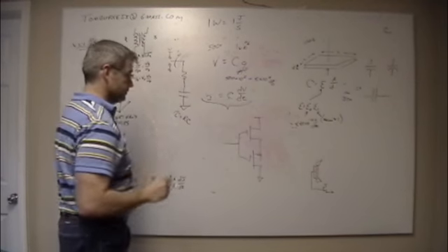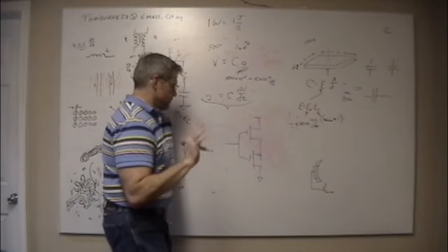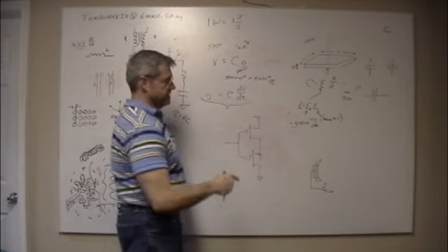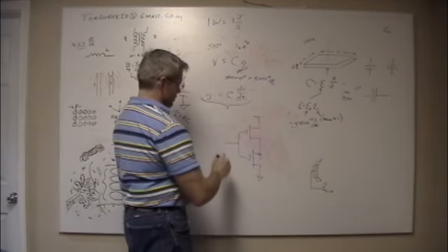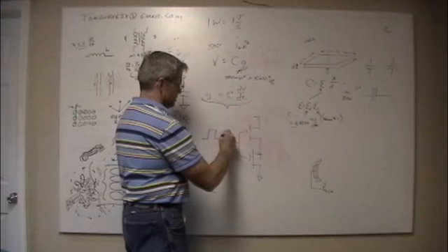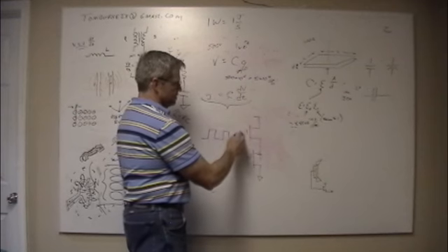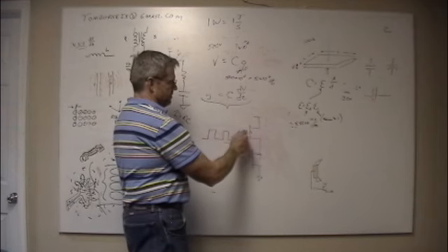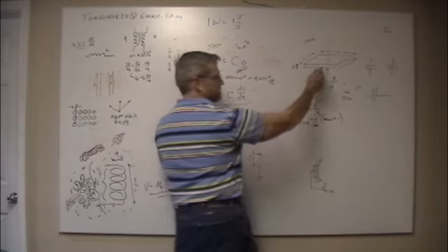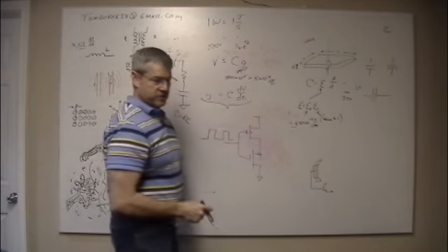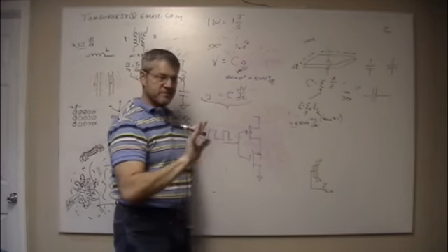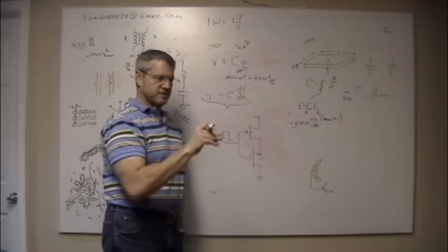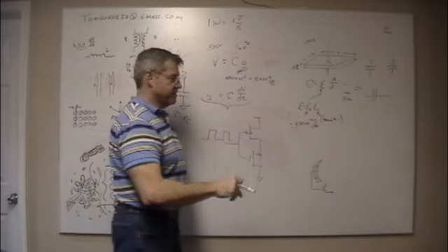All right. Now, there are 2 things that happen. The gate of a field effect transistor is actually a capacitor. So whenever a signal comes in, it charges. When it charges, though, that's current moving through, right? Because I'm pulling electrons from this plate and moving them over to that plate. So that's current flowing. It stops DC. It's not trying to move it anymore. But an AC signal goes right straight through it because you're doing this.